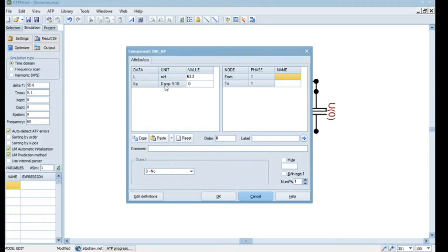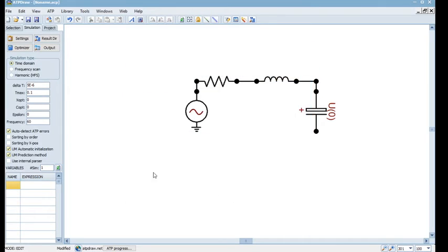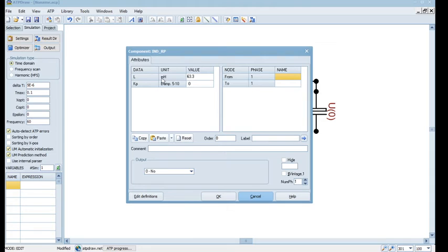So you need to notice, and whenever you are making a circuit appropriately, you need to set this. And why have they done this? Because this is required very much in some kinds of simulations. So we set everything to default to begin with. So we are specifying inductor and capacitor, not reactances.